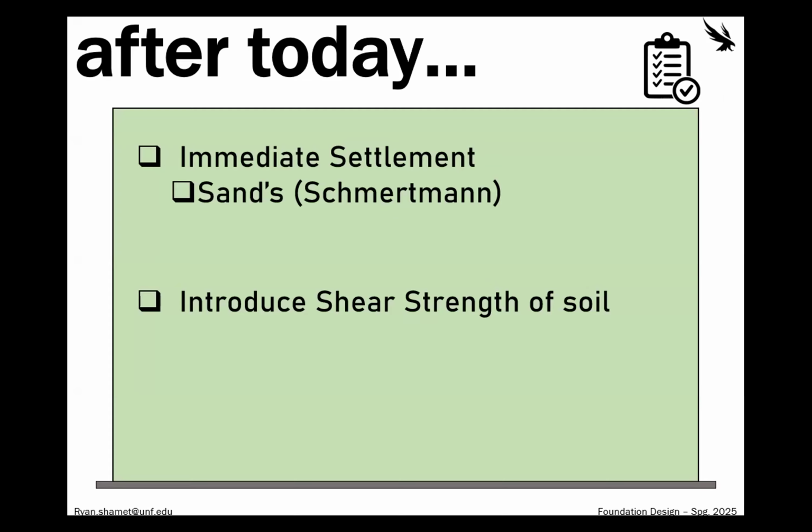The Schmertmann method too. Let me go to a pen. This is a cool one because this is an empirical technique. So if you remember, or if you haven't watched the lecture yet from Monday, those methods like the Bowles methods and all the elastic settlement methods, that's based strictly off of the theory of elasticity. So that's strictly theoretical, same kind of with Boussinesq and all of those things where we talked about the delta sigma z, the increase of stress. And that's good to a certain extent, but really the heart of geotechnical engineering and foundation design is empirical.